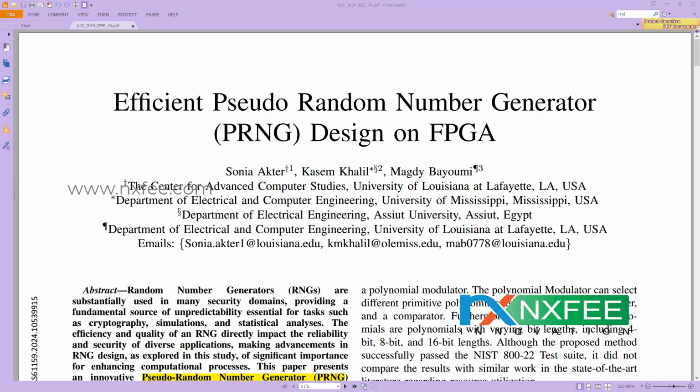To mitigate these issues, a dynamic soft reset mechanism is implemented, automatically reinitializing the seed whenever a repeating pattern is detected. This ensures a continuity of unpredictable sequences without manual intervention. These PRNG designs are implemented and tested on FPGA platforms with performance metrics including repetition duration, power consumption and resource utilization analysis for each polynomial configuration.